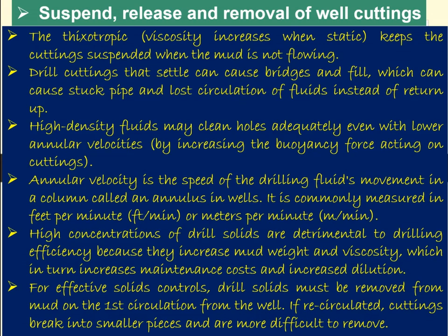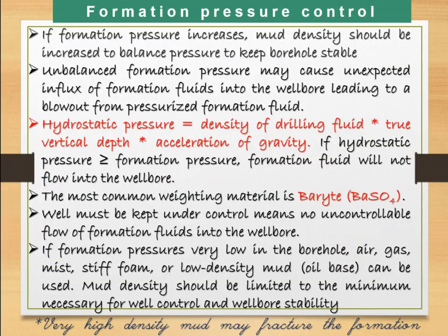High concentration of drill solids is detrimental to drilling efficiency because it increases the mud weight and viscosity, which in turn increases the maintenance cost and increases dilution. So from this we can easily understand that we need to have a balance, neither very low concentration nor very high concentration. For effective solids control, drilling solids must be removed from the mud on the first circulation from the well. If recirculated, cuttings break into smaller pieces and are more difficult to remove. So we need to understand these things.